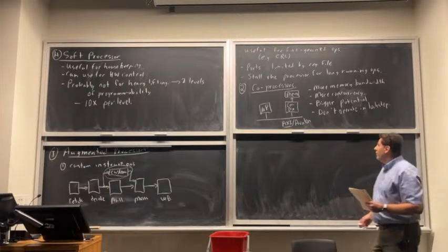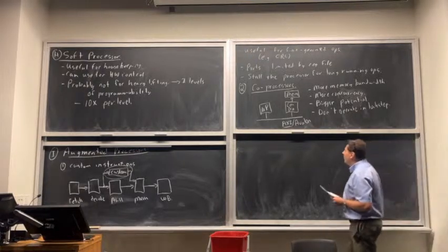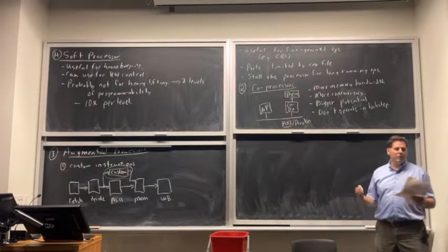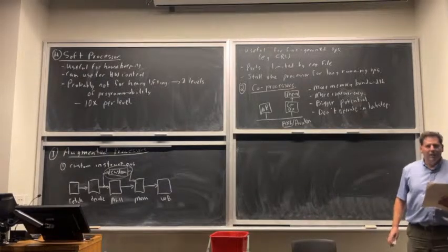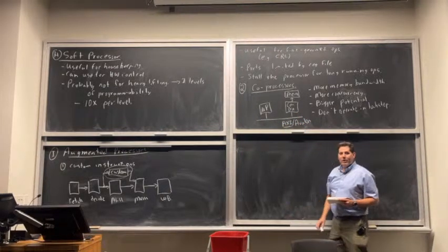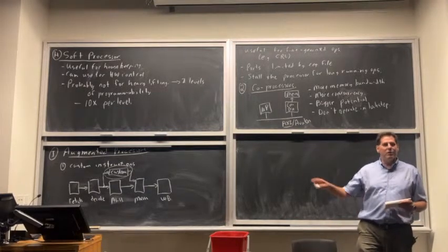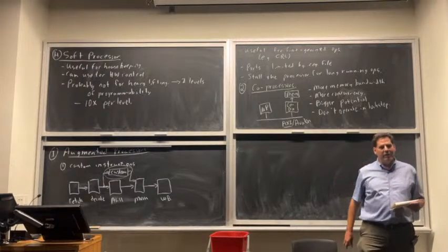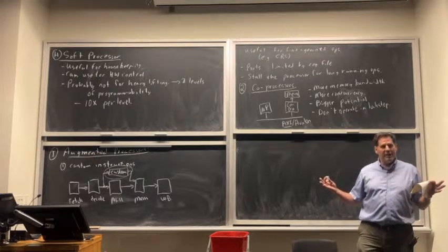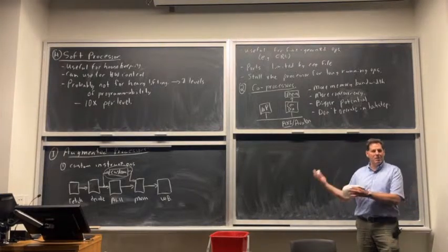So for a coprocessor, your example of digital signal processing could be one. Let's say I needed to do a big filter, or I think you said a fast Fourier transform. So the microprocessor could basically write over this bus: at memory address 100,000 there are 1 million data points, and I want you to do an FFT on them and store the result at address 2 million. So it only sent maybe 3 numbers across that bus. And the data already has to be in memory. Maybe it's on-chip memory, maybe it's off-chip.